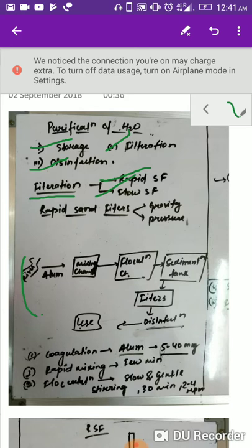So this is the river. This is the source of water, which contains a lot of impurities, and we have to make it suitable for use. So there are certain steps that we go through. The first is coagulation. So here you can see coagulation. What we do is that we fetch water from the river and then we mix alum, nearly 5 to 40 milligram, depending upon the different physical properties of water, its pH and other things.